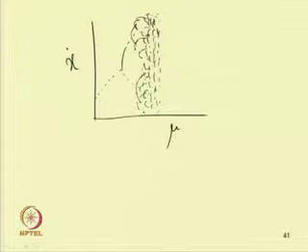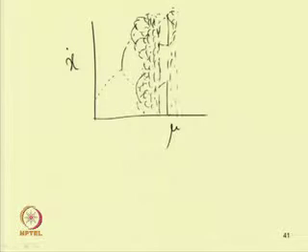So, by changing this control parameter, initially one has a single period, represented by a single point, then it becomes 2 period, then this 2 period becomes 4 period and 8 period, 16, 32, and in that way. So, one can find a window. In this window one may have 3 windows or 5 windows, and after that again one can have this chaotic response. This way, by using the Poincare section, one can distinguish periodic, quasi-periodic and chaotic response.